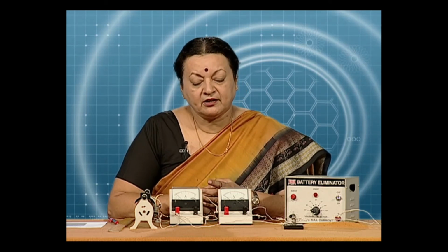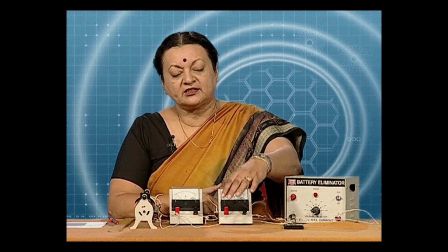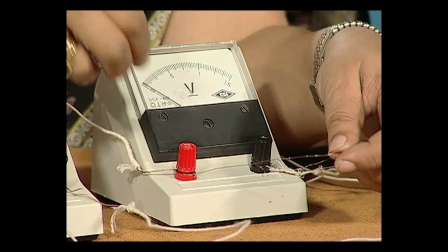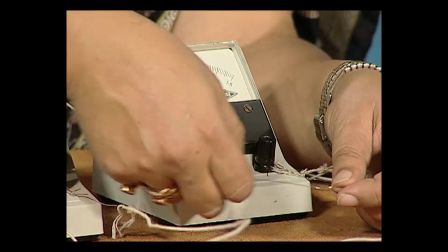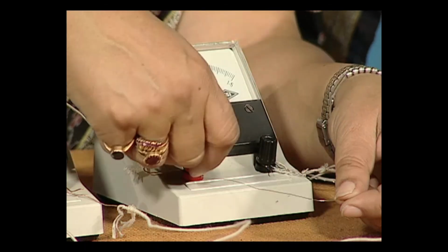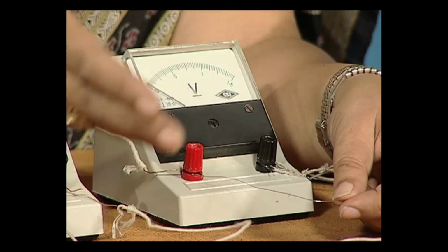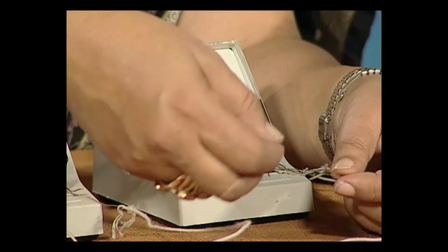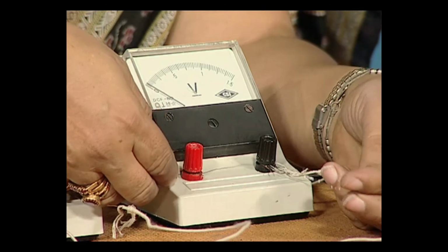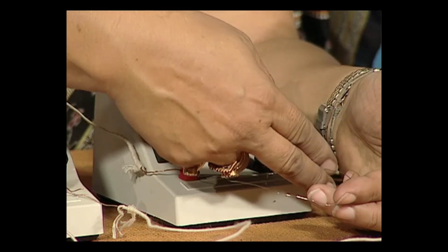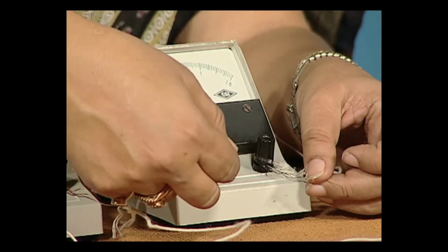And what extensions can you do? How can you do more project work with this? You can find out how much of the resistance is there for a wire by using a crocodile clip instead of placing it here, taking a definite length. You can choose different lengths by keeping this wire end loose, connecting a crocodile clip to the other and connecting at different lengths, and therefore putting that in the circuit. So, you can have a variation with that.